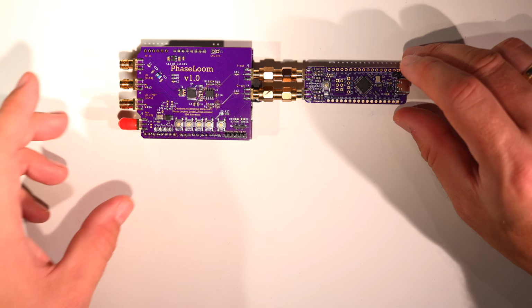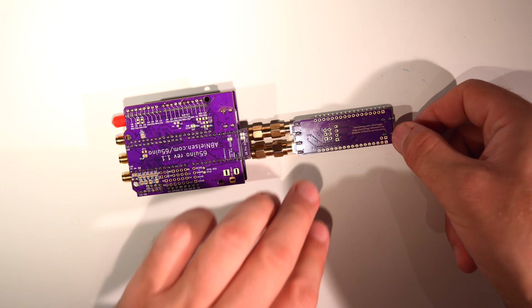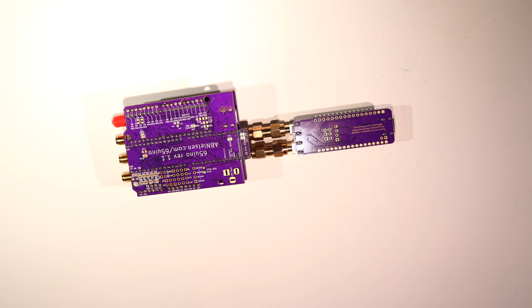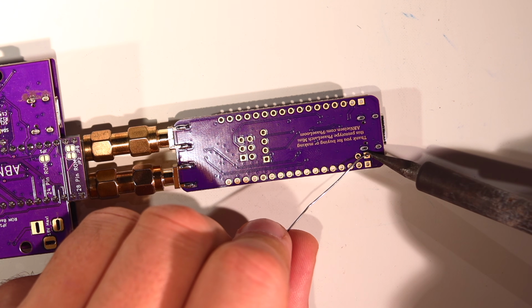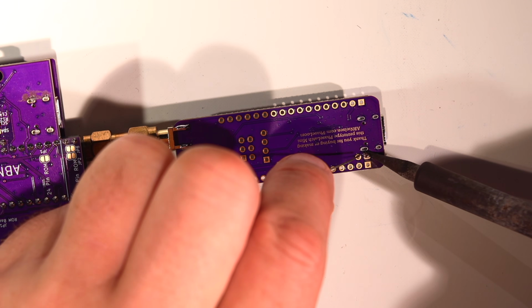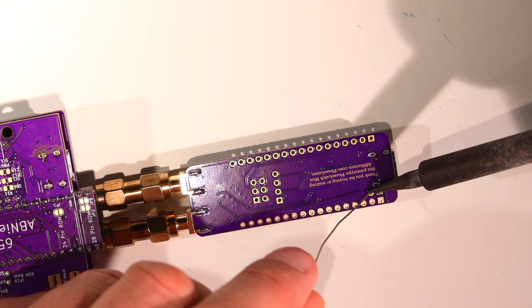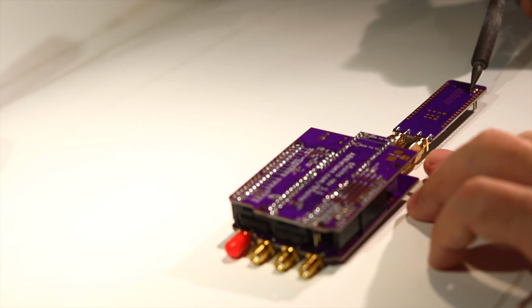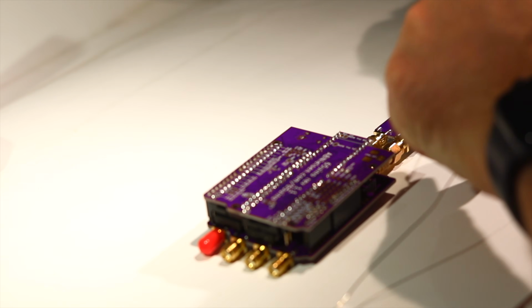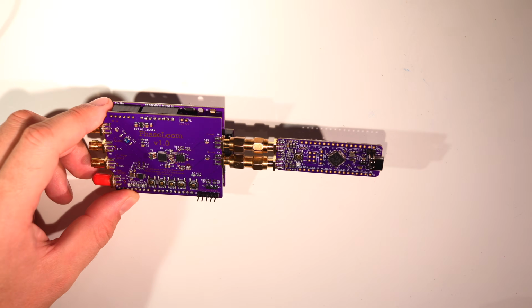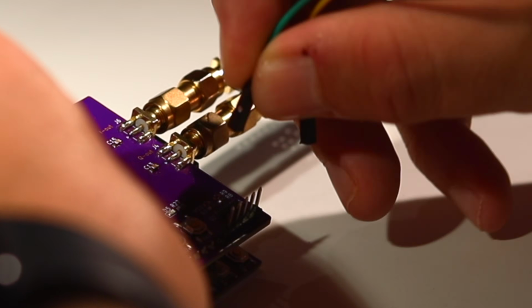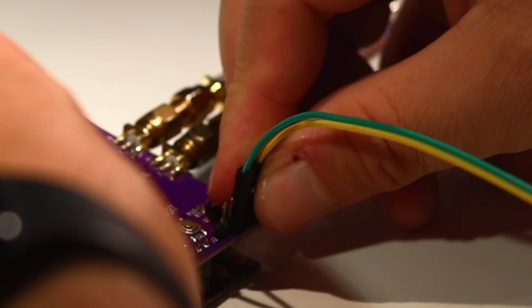Since I've already programmed the Arduino Uno to control the PhaseLoom, I don't need that hooked up to USB as well as the new board, so if I solder on a header for the 5V output, we can use a single USB cable to power all the boards. Of course, I could just add the code to control the PhaseLoom over I2C from the new board, as well as acting as ADC and USB bridge, but for now I'm happy using both. Besides, I will be going down a different road with a bunch more bandwidth anyway. More on that later. Let's see what this can do.